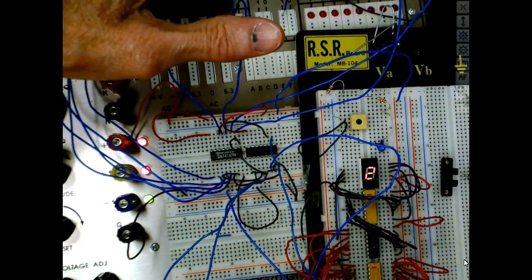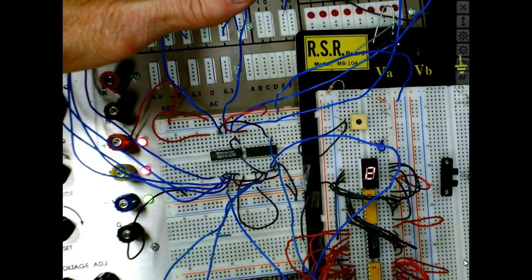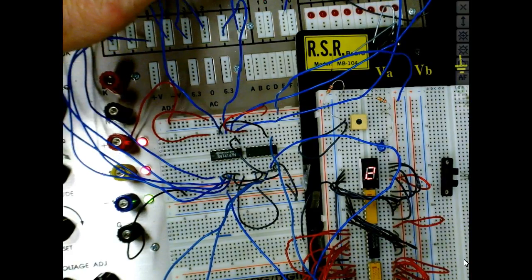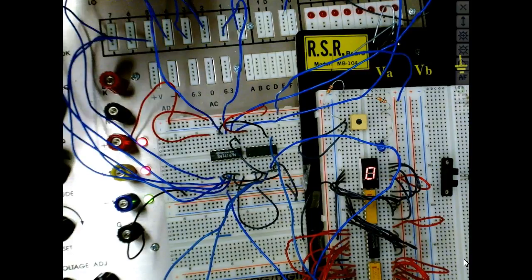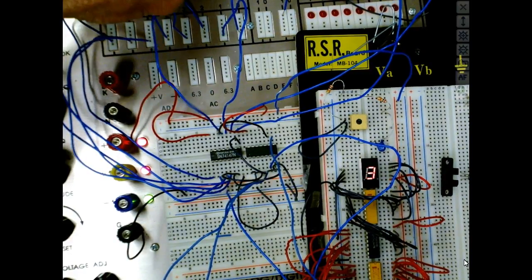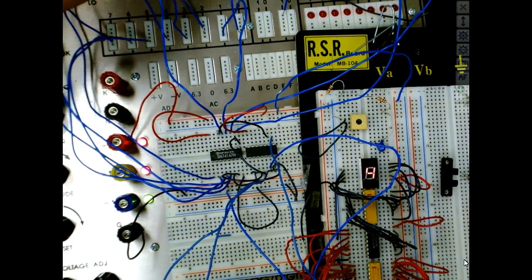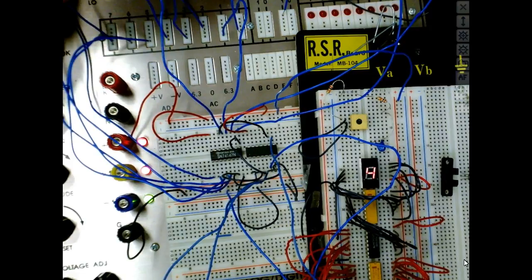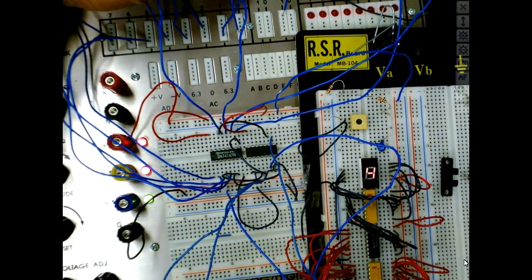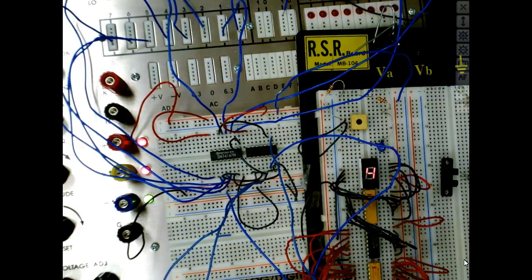It should display a what? I'm having problems with my 2 switch. It's going to display a what? A 2. Input 3 should display a what? A 3. Input 4 should display a what? A 4. But if I bring input 1, it doesn't do anything because input 4 has a higher priority than input what? Than 1. And that's why it's called a priority encoder too.